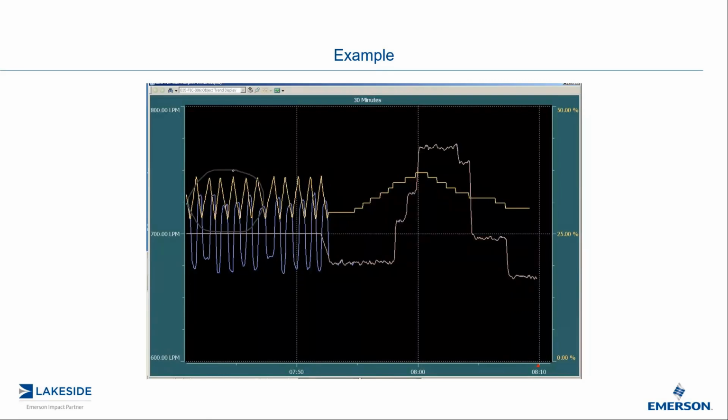And so we didn't know what that value was, but obviously deadband was set to some high value because you can see here 1, 2, 3, 4, 5% before we got a change in our flow. So it was a very significant imprecision. So what we did, we could actually set this deadband value in software through AMS or through a HART communicator, and we put it in manual, and then we set the value to, I think it was like 0.5%. And then lo and behold, the valve problems all went away.